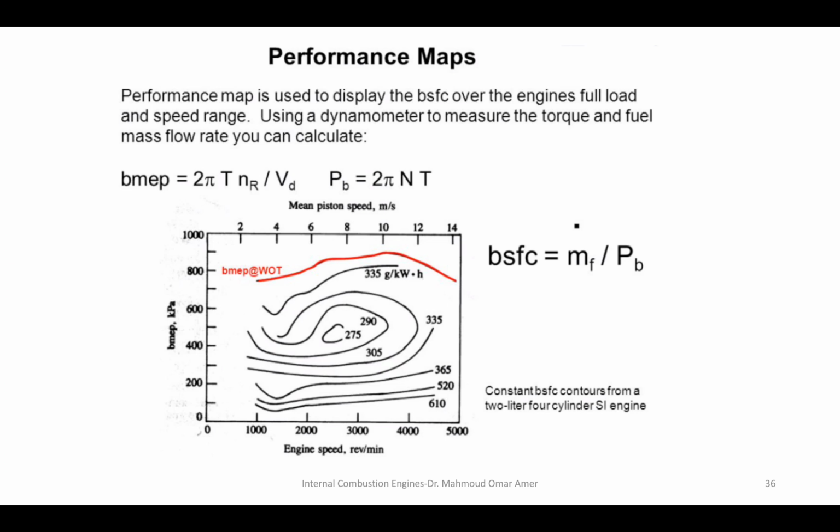How do you calculate the stroke? You take any value, maybe this 6, it equals 2LN. You go down and find the corresponding speed. The only unknown is L, which is the stroke. That's why I said at the beginning you can assume a square engine if I didn't give you any indication on how to calculate the stroke.